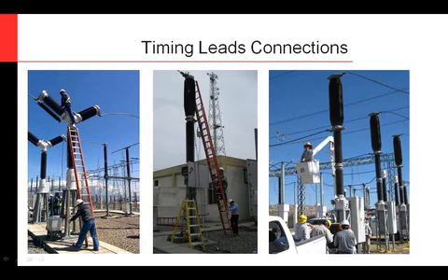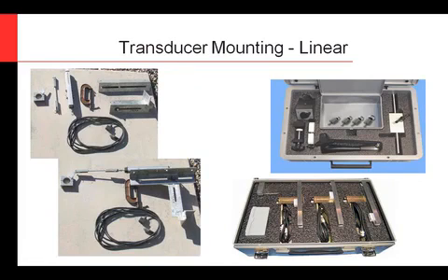Of course, the next thing and the most complicated thing with circuit breaker timing, I wish I had an easy way to do this, but really each breaker has to be evaluated for its factors. Some manufacturers are very good about giving you pictures. Other ones, especially some older designs, you might have to figure out on the fly in the field.